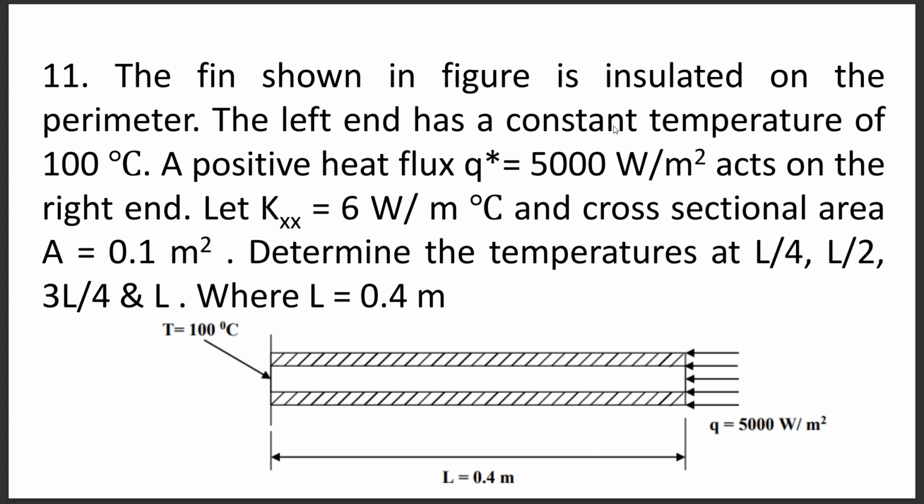This problem cannot be solved using link. This is a completely different type of problem. As we are providing heat flux from the right-hand side, it cannot be applied on a specific node. We need either more than one node, or a specific surface to apply heat flux from any specific surface or line. So we need to model this a little differently compared to the normal method. Without wasting time, let us start our analysis using ANSYS Mechanical APDL.